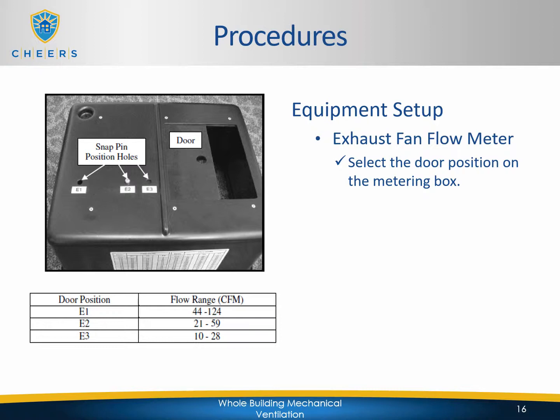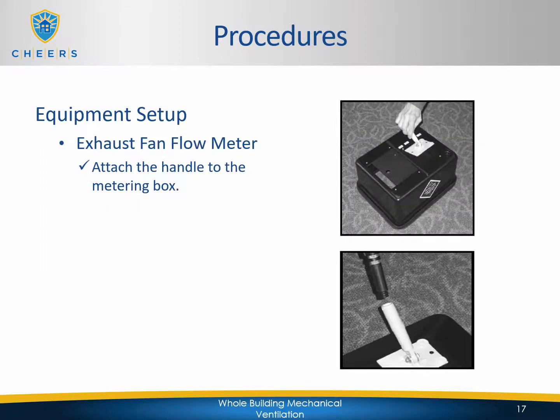You will practice doing this particular test with a flow box when you're actually in your field training. So you'll be practicing this hands-on. This is just to give you an idea of what the equipment looks like and the setup procedures. Specific setup procedures for the gauge and manometer will be going through with you during the field training as well. You then want to attach the handle to the metering box.